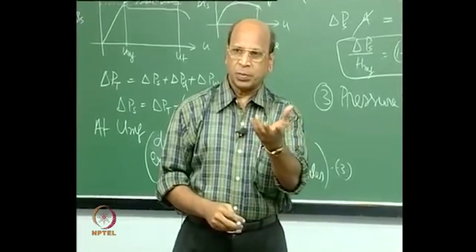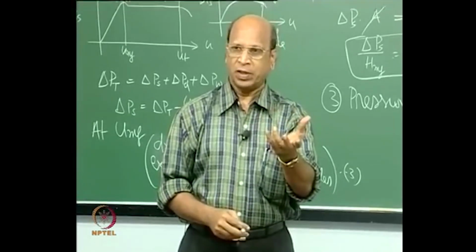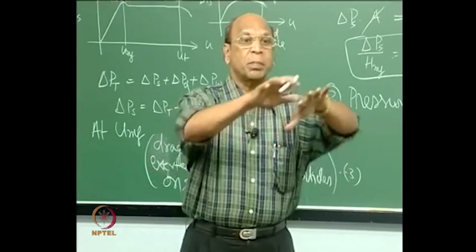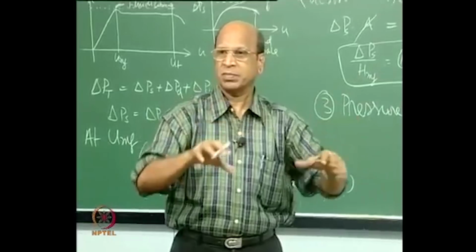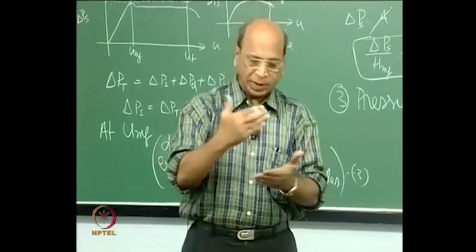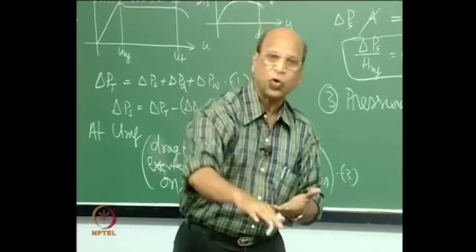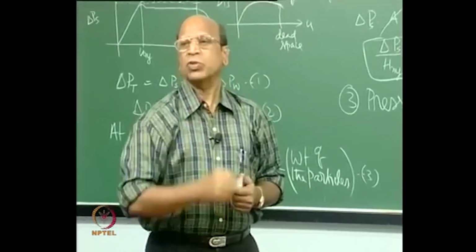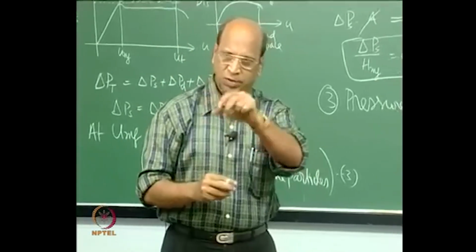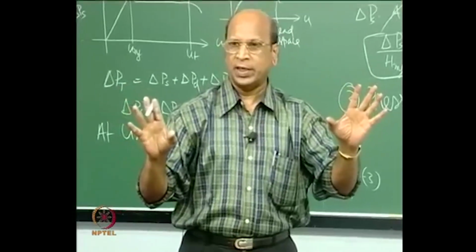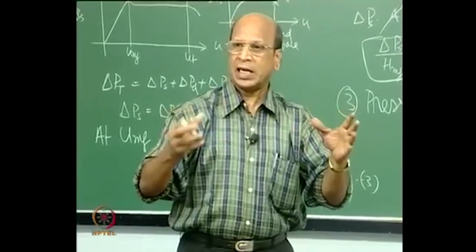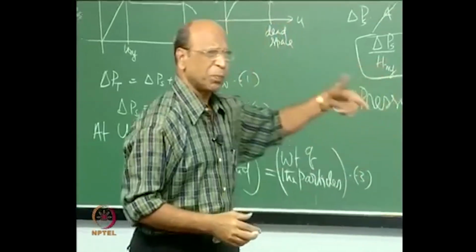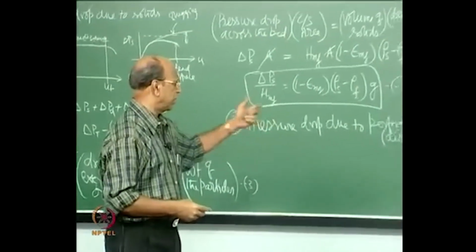Here perforated plate is the best one, sieve plate is the best one. And sometimes what we do is, over the sieve plate we will put mesh, very fine mesh, so that it will not create any pressure drop, but it will not allow solids to fall through. When they are falling through, it may block even sieves. So, then you have that hole totally not used for the flow, then you have the dead space, and if you have more dead space it will create problems. You see, everything is important when you are designing any equipment.